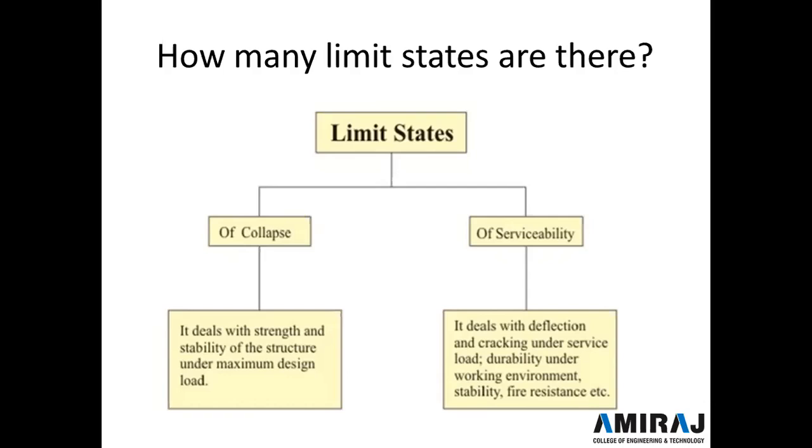Ultimate limit states are those catastrophic states which require a larger reliability in order to reduce the probability of their occurrence to a very low level, right? These are associated with failures under the action of the probable and most unfavorable combination of loads on the structures. So, without using partial safety factors, we may endanger the safety of life and property.